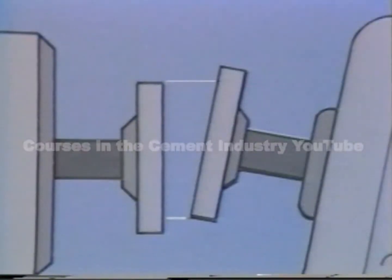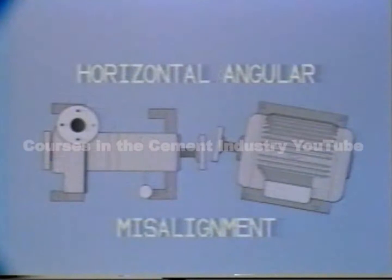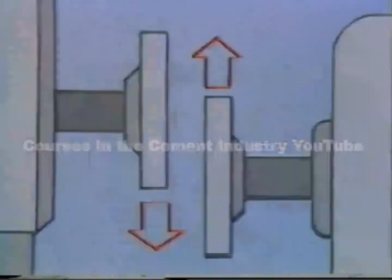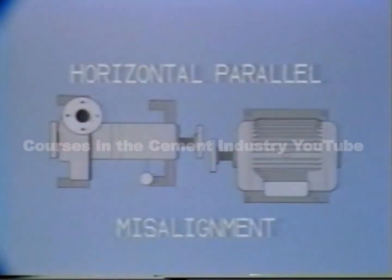Angular misalignment is detected by measuring the distance between the coupling halves. Variations from top to bottom mean vertical angular. Side-to-side variations mean horizontal angular. Parallel misalignment can be detected by measuring the offset between the coupling halves. High or low offset means vertical parallel. Side-to-side offset means horizontal parallel.